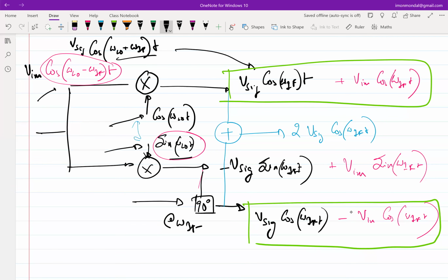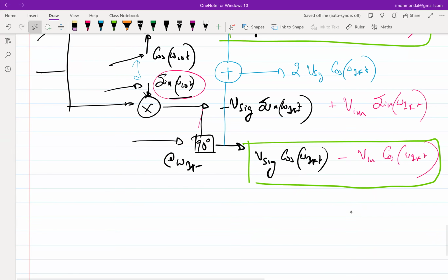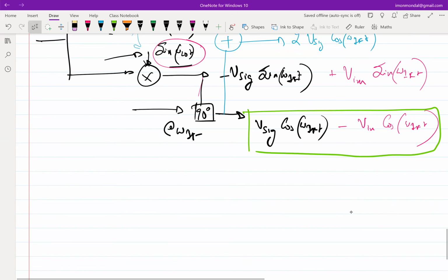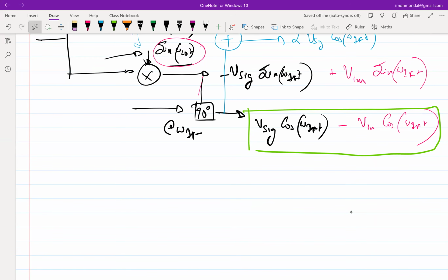Similarly, I do not have time today, but you can also show that if you have differences in phase, you can have such impacts, right? Now, coming back to Dhruv's question, how are you going to create a phase difference? So again, what is a phase difference? If I say the two waveforms are 90 degrees apart, in the time domain, what do you interpret it as? It's a delay, right? So here I have shown only sinusoidal clocks.